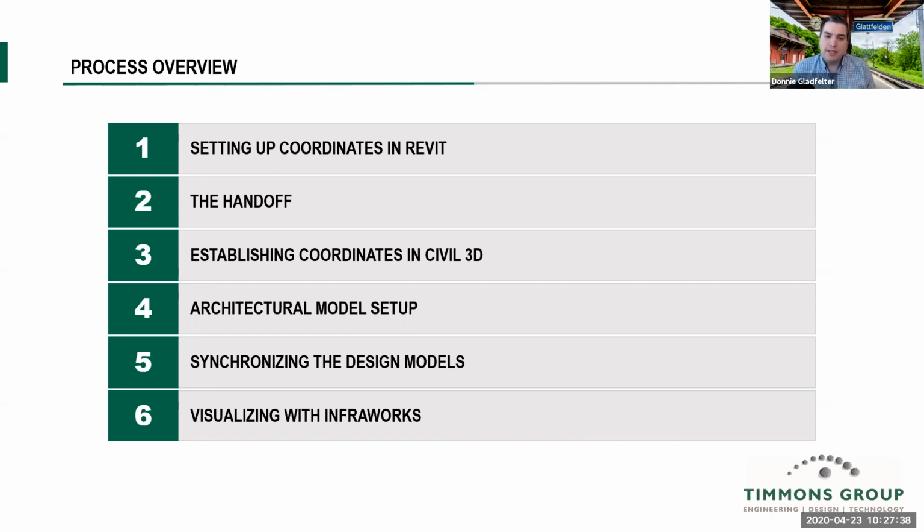I forget the release. They all kind of start running together for me. We did finally get an OR parameter. So for many years, when we created view filters in Revit, it was only an AND parameter. So it had to qualify for all of the rules that you applied to that particular view filter. Again, I forget the version, but we also got an OR.